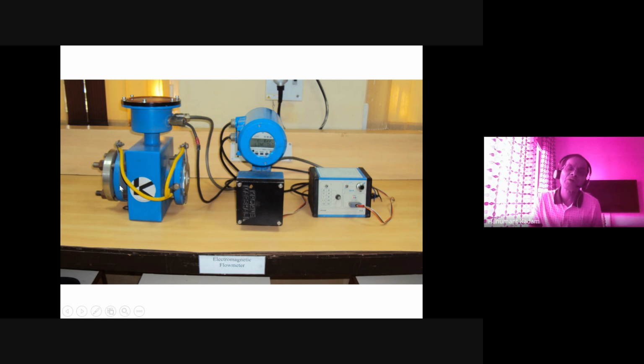I'm not talking about the electrode simulator. Electrode simulator is done in the flow lab, especially designed for various sizes of the flow meters. Means, as I told, 1 inch pipe, 2 inch pipe, 3 inch or 4 inch, as per DN size. Flow calibration means a particular organization develops their setups, or sometimes they send it to outside labs, where they only do the testing calibration of your fluid. So you have to send it there and calibrate it.